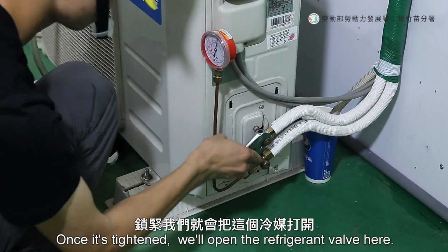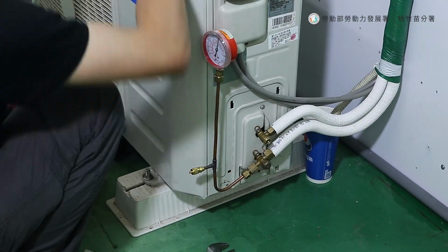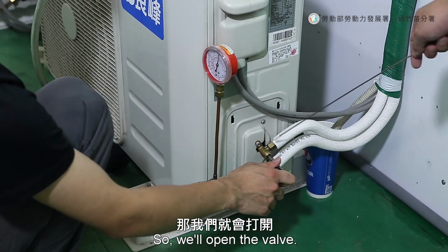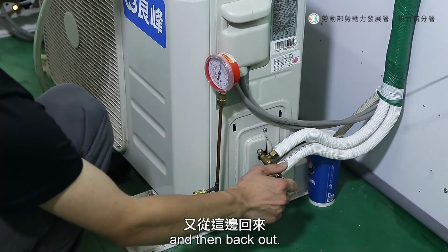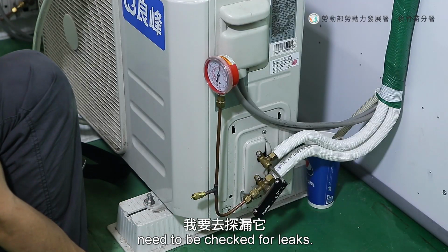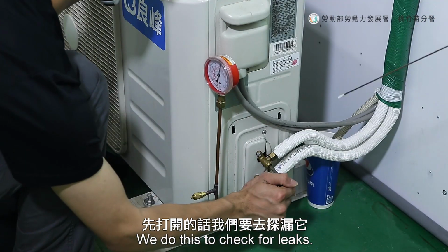Once it's tightened, we'll open the refrigerant valve here. Because during installation, the indoor unit ran out of refrigerant, so we'll open the valve to allow refrigerant from the outdoor unit to flow into the indoor unit and then back out. The two flared openings connected earlier and the two openings behind the indoor unit need to be checked for leaks. So we'll open the refrigerant valve. We do this to check for leaks.